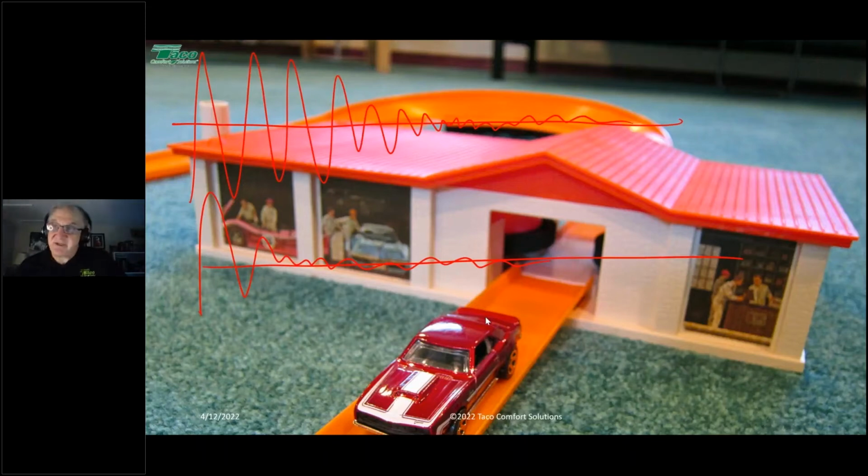Always look at the numbers, because if you go down a size, depending upon who makes the valve, it might really be a low CV, high pressure drop valve. So just check the specs, but I think what you're looking at there, Steve, is a good basic approach.